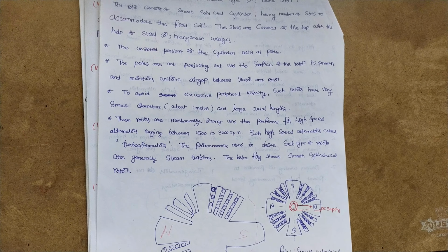The length required for end connections of the coil is less, because if you use the full pitch coil, the end connections need more copper. But if you reduce the coil span, the length of copper wire required for end connections is reduced. That is, the inactive length of winding is less, so the copper requirement is less and it is economical. Another advantage is that short pitch eliminates high frequency harmonics.